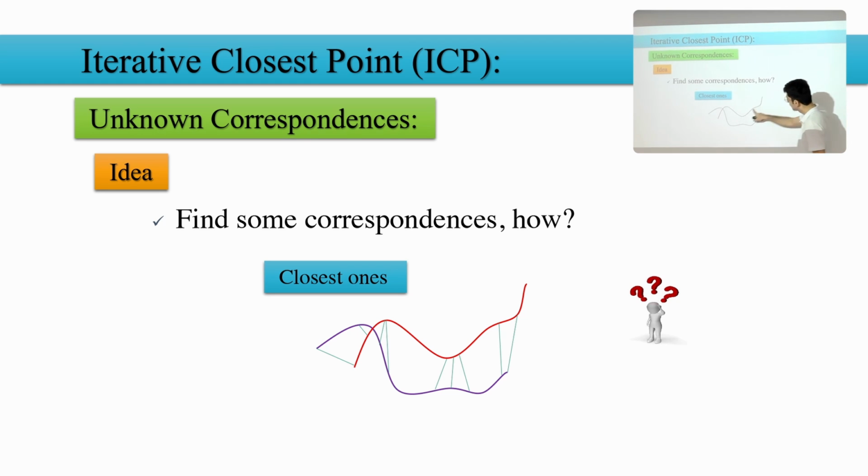We have this point cloud A, and this is point cloud B. The robot is moved, and it scans A, scan B. Then the closest point says, okay, for this point over here, what is the closest point of the other cloud? Minimum closest point, maybe this point. For this point, what is the closest point of the other cloud? You measure the distance, this is the closest. For the purple one, this one, what is the closest point? Maybe this one, this one, this one.